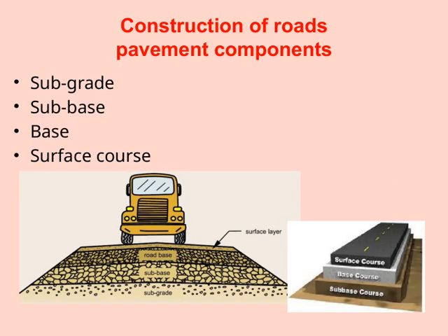Let's take a closer look at the construction of roads, specifically the pavement components. Starting from the bottom, we have the subgrade, which is essentially the natural soil prepared to support the layers above. It's crucial because it provides the foundation for the entire pavement structure.